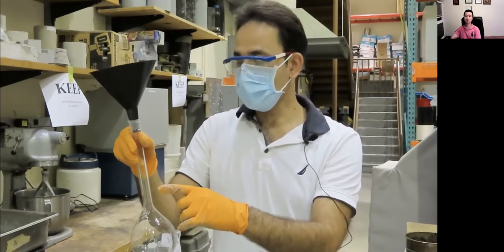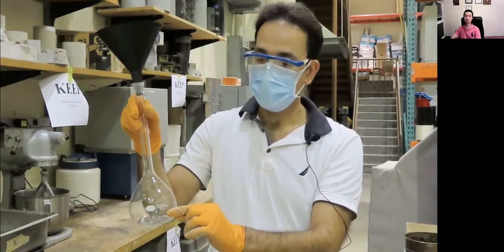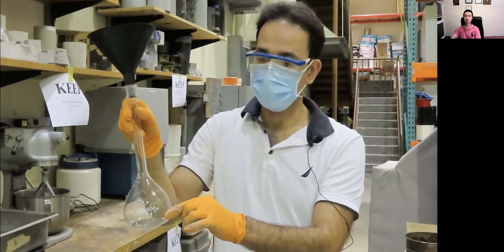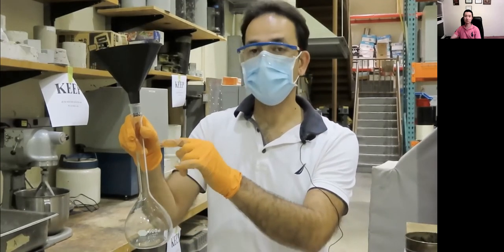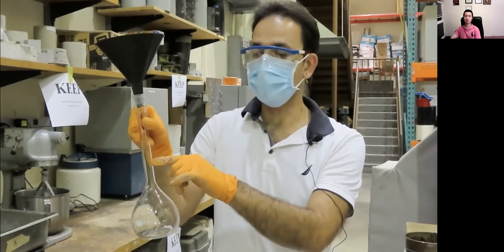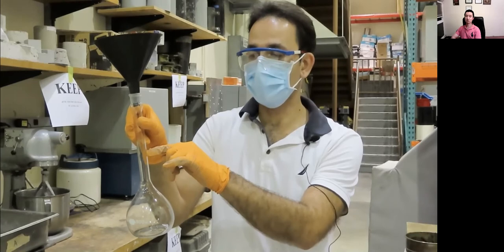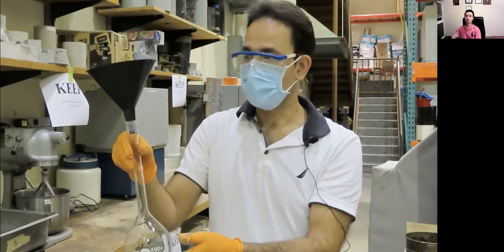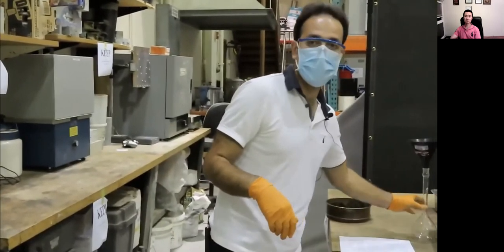So what I need to do is grab a little bit of water and pour the water in up to here, dump the aggregate inside, and add more water up to maybe 90% of the pycnometer, so that 100% is in here that I'm going to show you. I'm going to get closer. So I'm going to get some water and get back to you.